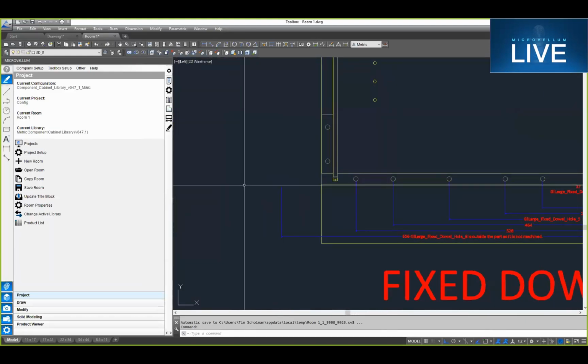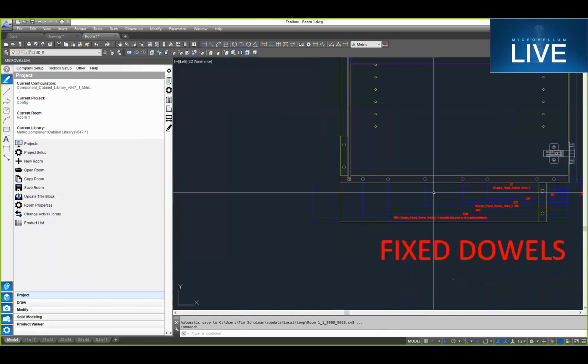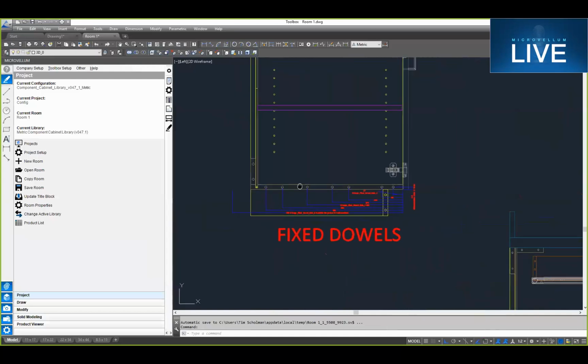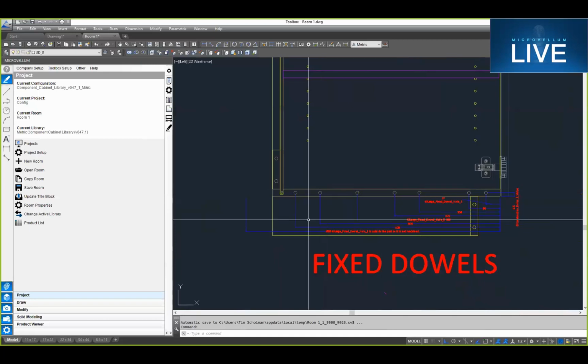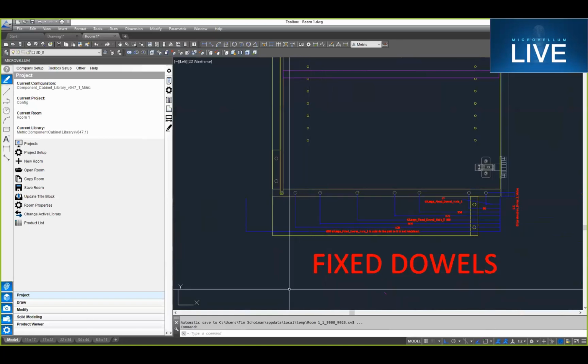So that system works really well with a fixed head drilling machine where you're horizontal boring on a fixed pattern, and you don't want to ever have to adjust the horizontal machine, and the CNC will take up for the vertical drilling in the cabinet sides in order to address that type of pattern.